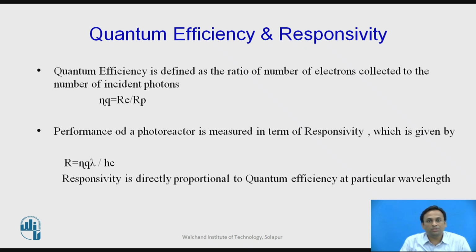At the demodulation, when the maximum amount of light is incident on the PIN diode, the avalanche photodiode or the phototransistor, more and more electron and hole pairs will be generated. That is connected in the reverse manner here. So whenever light is incident on it, more and more electron and hole pairs get attracted towards the positive and negative terminals of the PIN diode.